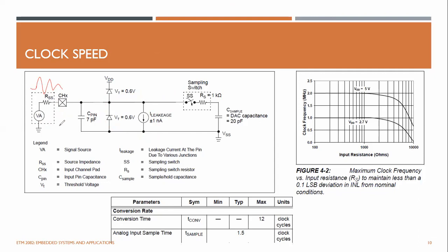Even if you connect a resistor divider, for example, to a battery with R1 and R2, and couple this pin, let's say VC, to an ADC channel node, then looking from this point, it should be equivalent to a voltage source and a series impedance.